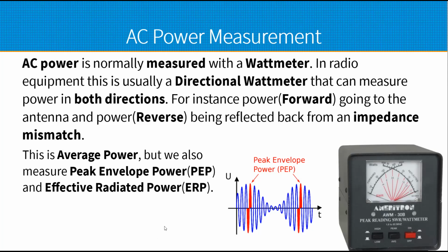And the ARRL site has a calculator and you just put in the numbers, what your power is, what your duty cycle is based on the type of modulation. Well, for different frequencies, from 30 to 300 is worst case. It's 1 milliwatt per square centimeter for humans, because your soft tissue like eyeballs is the most susceptible at those frequencies.